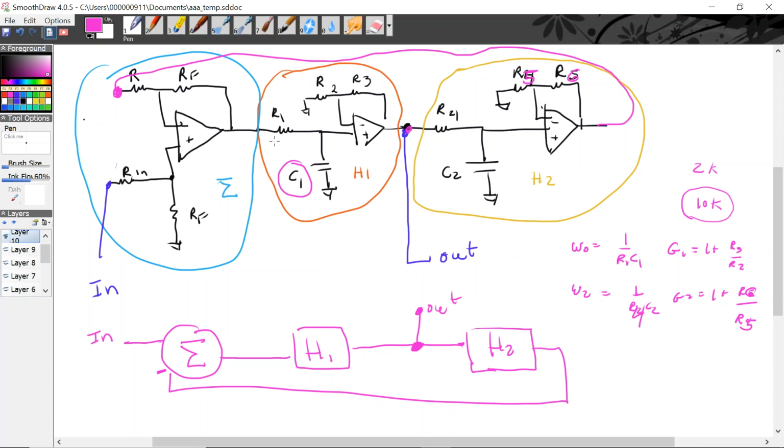Now, sometimes you have to go less than that, but a lot of things have 50 ohm series resistance coming out, so you want to be 100 times bigger than that. Otherwise, you're going to get a voltage division, like a non-ideal voltage source. So you can choose 1 micro or whatever. There are some common values you choose, because there are always more choices of resistors than capacitors.